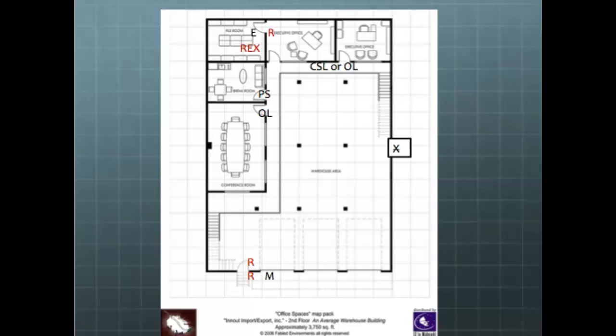You put the cipher lock on and you have a storeroom function so that it stays in a constantly locked position. Jumping back, though, to those executive offices, there was one person I saw that put storeroom locks on those doors. Certainly it would work, but people who are in executive positions, people who are in management positions, don't tend to carry their keys around with them all the time. And every time they walk out of the room, the door's going to close and it's going to lock, and their keys are going to be on the inside. And about a week of that, you'll be changing the lock, which is why I think a storeroom lock set in that regard is a very bad idea.